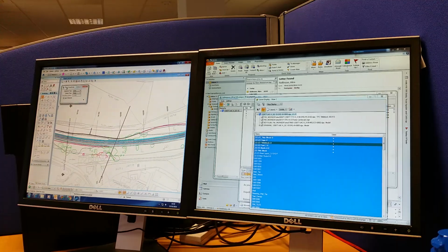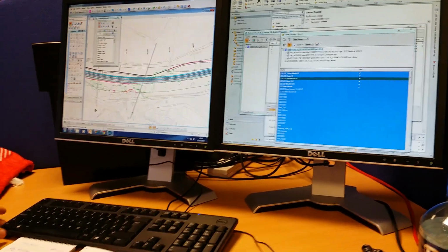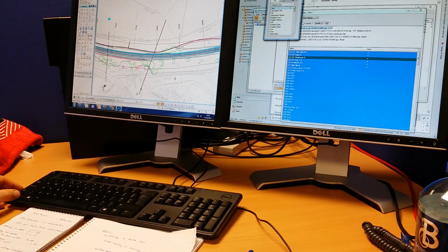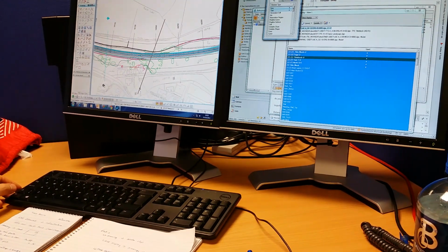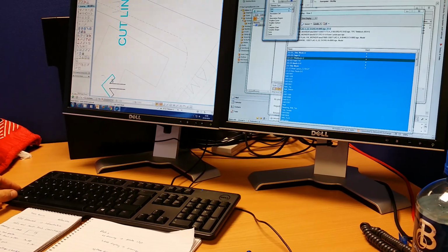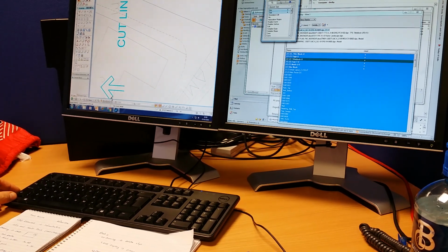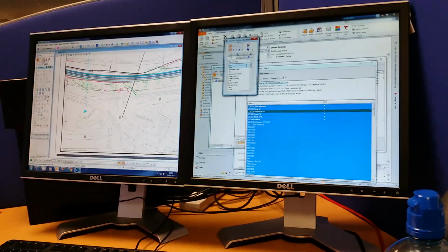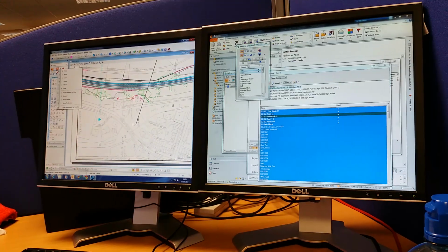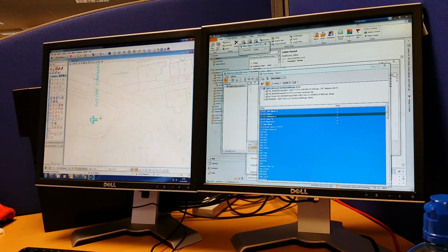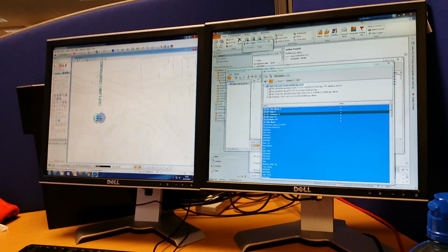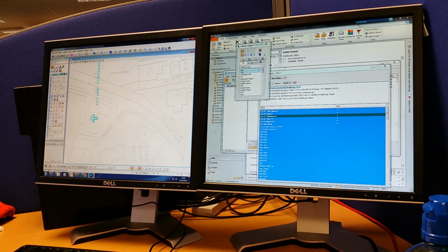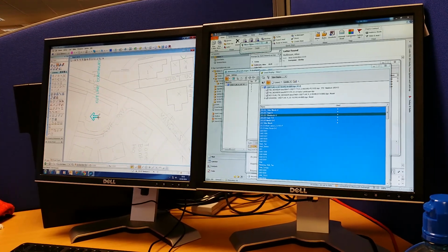So now we can select the arrows and the text that needs moving. Press and hold Control to select more than one item. And select move. Pick your base point. Before I do that, set that back to key point, otherwise you don't select the end, so it's move.